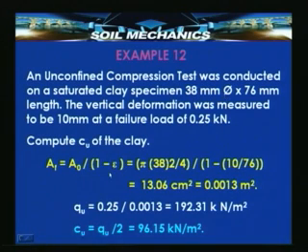On the other hand, since the deformation takes place in the vertical direction as the load is applied, due to the Poisson effect, the horizontal diameter increases, and there is a deformation taking place in the horizontal direction, which therefore makes the effective area slightly different.